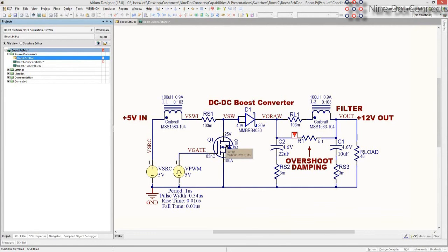So the rate of change of current is much lower because the device is so big. The inductance is low because the vias are huge, which helps lower the inductance of the via, and just because it's so big and it just can't move that fast. And again, that's one of the reasons why if you start saying, I want to build a switching power converter and switch at 100 megahertz, you conceivably could do it, but all of these other effects would start coming into play. If you're switching down in 100 kilohertz, almost nothing comes into play at a megahertz.